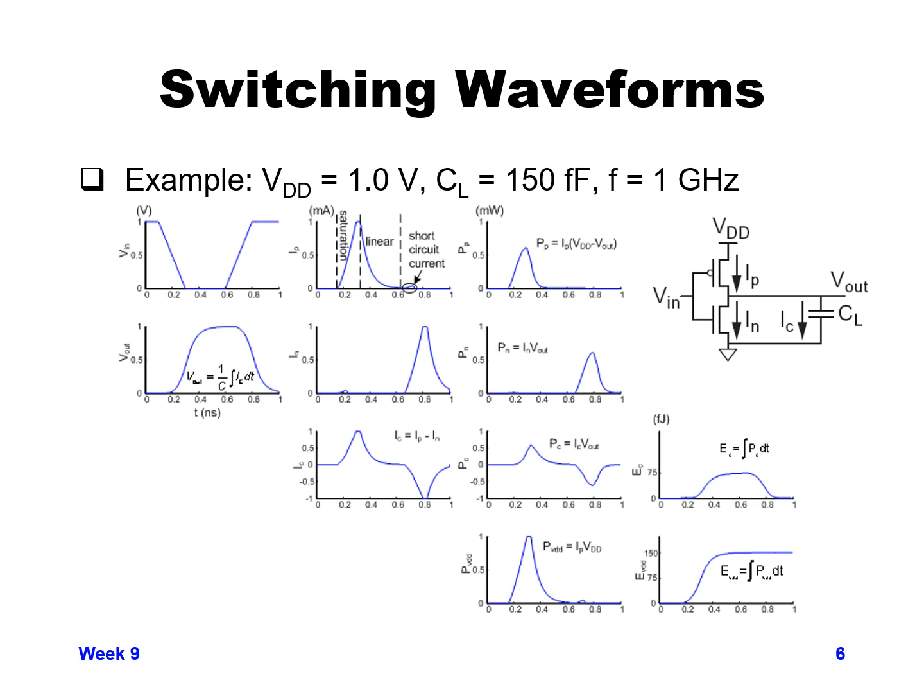Let's look at the columns. If we go to the leftmost column, we have V in and V out as the top and second waveforms. V in starts at 1 volt and switches from high to low, down to ground. It stays there for about 0.2 to 0.3, I think that would be nanoseconds. And then at 0.6 nanoseconds it switches back from 0 to 1.